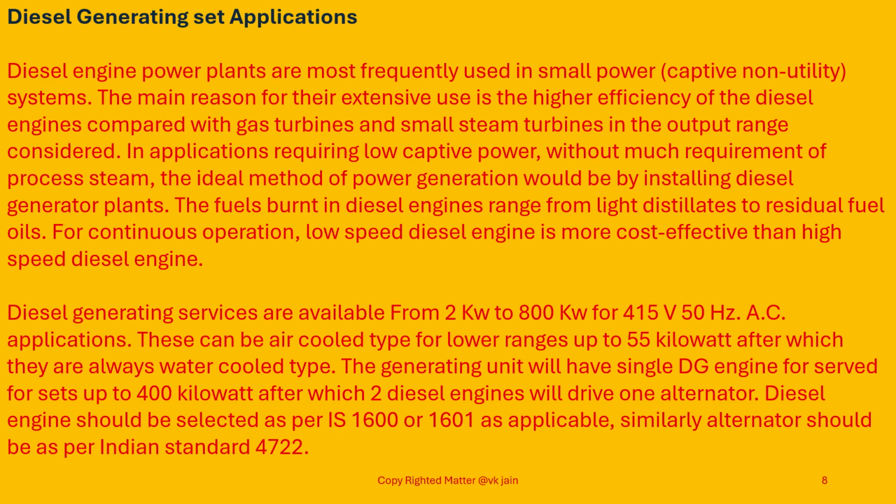Friends, now we'll talk of diesel generating set applications. Diesel engine power plants are most frequently used in small power, captive, non-utility. Non-utility means without electricity board. The main reason for their extensive use is higher efficiency of diesel engines compared with gas turbine and small steam turbine in the output range considered.